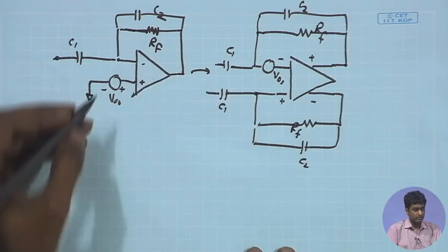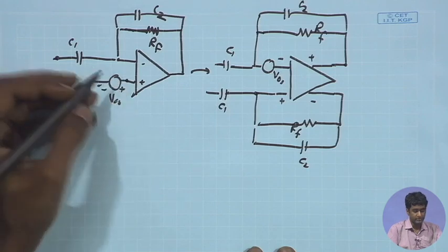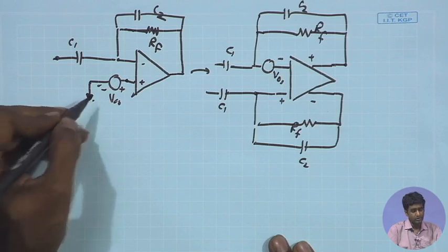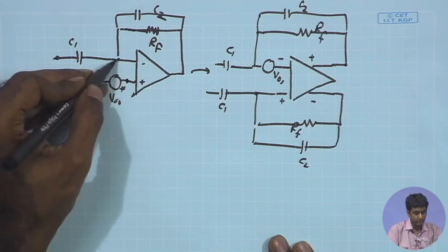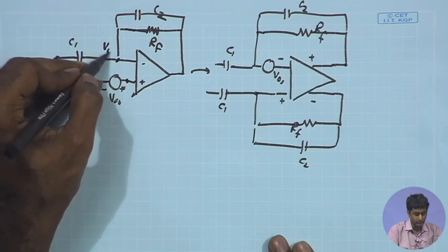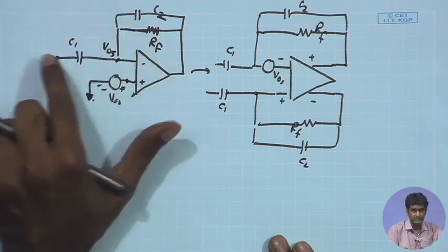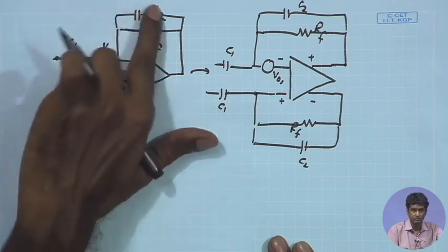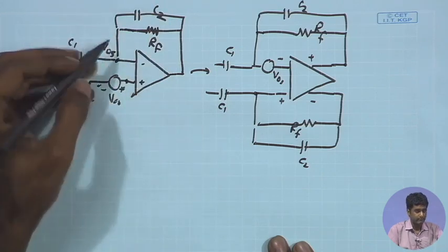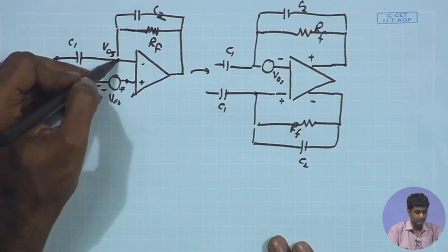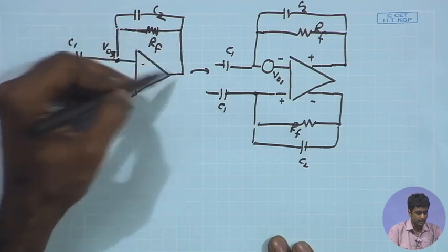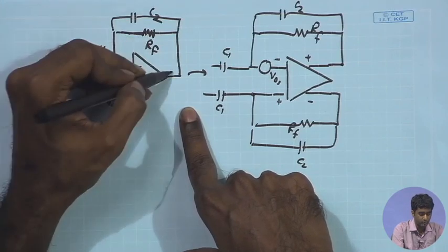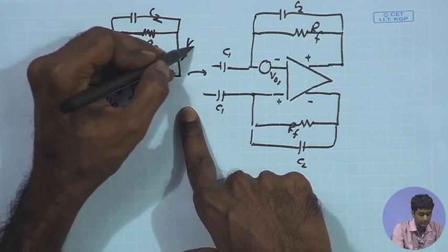Now, if I look at this circuit, 0 plus V offset. So, this is DC potential, means some VCM. So, of course, from AC point of view we set it to 0, and this is 0 plus V offset. As a result, this is also going to be the same point V offset. And if I look at DC, remember the capacitors do not have any DC paths. So, if I look at the DC biasing, they are not going to play any role, and if this is set to V offset, since there is no DC path in the capacitor, there is no current flow, the output should automatically be also equal to V offset.